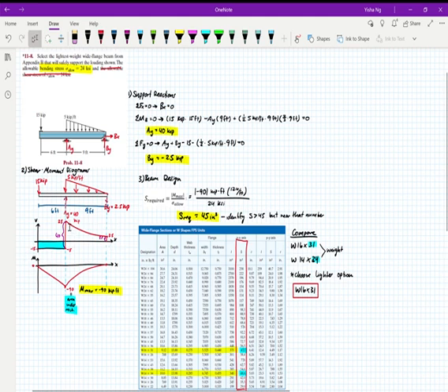So we go from 25 down all the way to 2.5, and we know that BY, which is a point force, is actually pointing down. So when you solve for the reaction supports, it becomes a negative value. So when I drew it here, I drew it downwards, being equal to 2.5. Anyways, so that causes our very last negative jump back to 0. So always remember that your shear diagram and your moment diagram start at 0 and end at 0. So that's a good way to check that your diagram is looking correct.